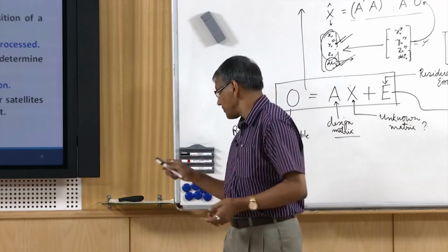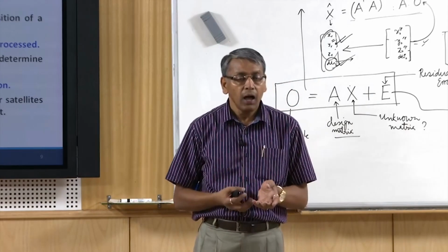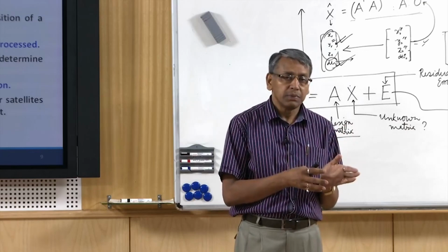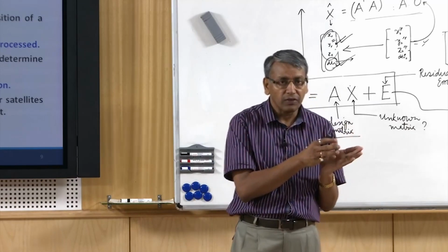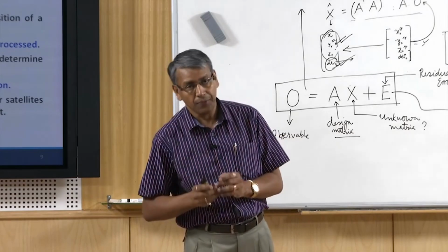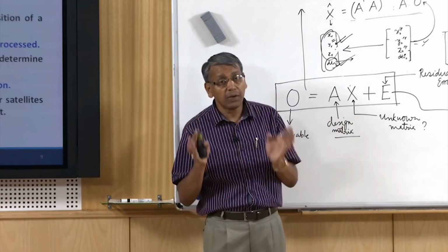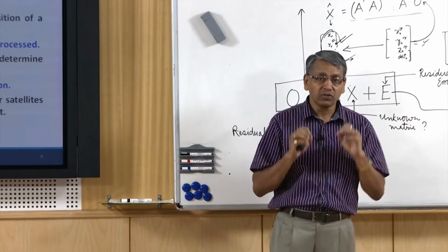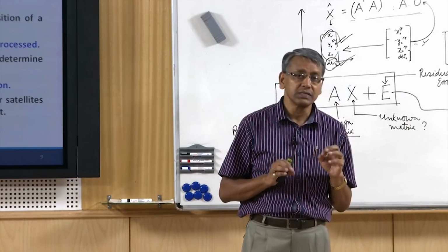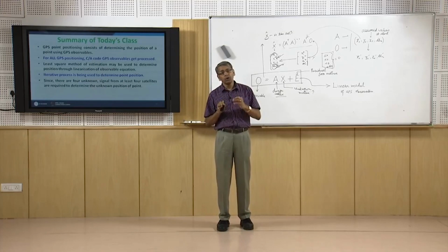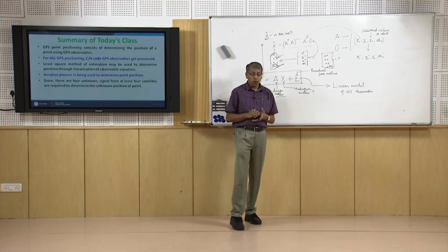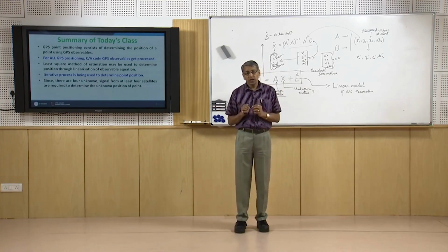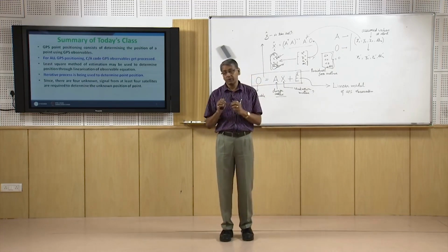There may be single code observation, there may be multiple code observables, or after processing the code we can take up the carrier phase. Whatever observables we take, whatever positioning methods we apply, the first thing we need to process is the GPS CA code pseudorange observables. So we need to find out the position of the receiver using the CA code pseudorange observables.